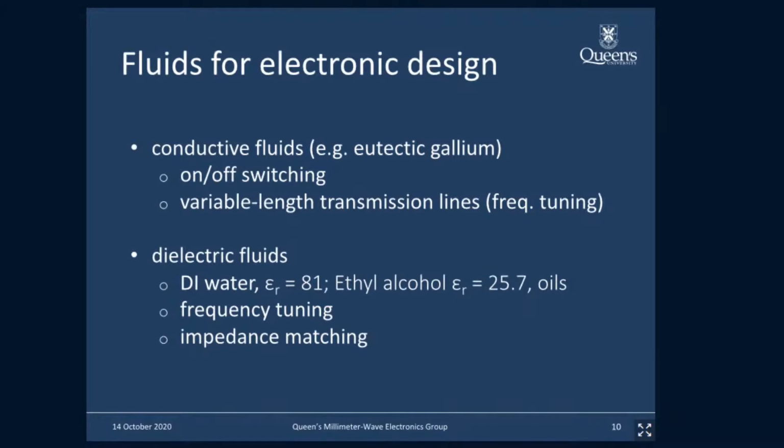There are other compounds that are not as lossy as water. Oils are not very lossy. Then you have alcohols, and there's a plethora of compounds that you can use. The question is, what is their permittivity? We've done a comprehensive study of many of these fluids, and we've characterized their permittivity response over frequency out to 40 gigahertz. That paper was recently published in the MTT Transactions, and we've put a numerical model to the data so that anyone can now use that data for their own simulations and designs.